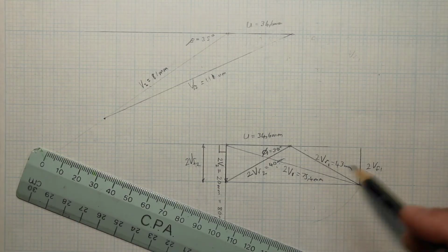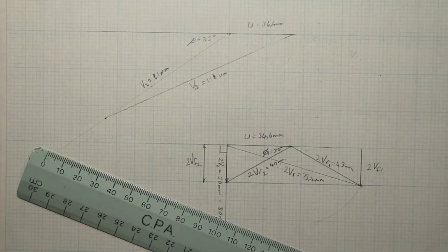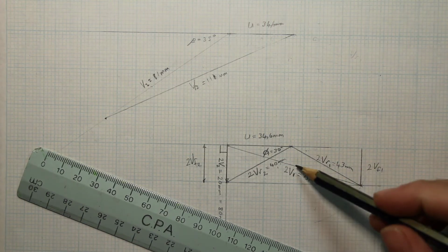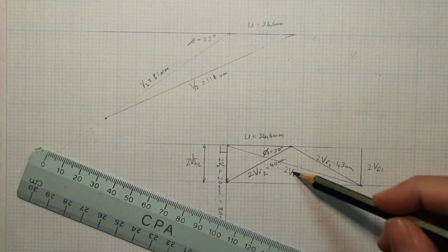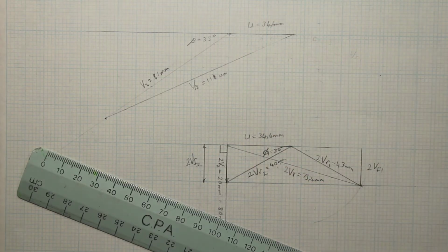Now we have to go from the second row of moving blades to the first row of moving blades. We know that the inlet steam to the second row of moving blades had to be faster than when it left the first row of moving blades.